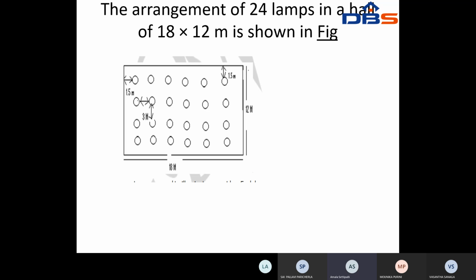Producing an arc between two electrodes is nothing but the arc lamps, where we discuss carbon arc lamps. Passing current through a filament or wire is nothing but the tungsten filament lamps. In discharge lamps you discharge vapors of gases, and we discuss many lamps: sodium vapor lamp, neon lamp, halogen lamp, and the compact fluorescent lamps, CFL.